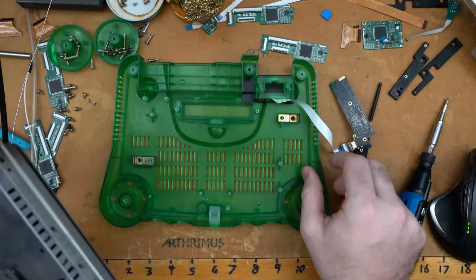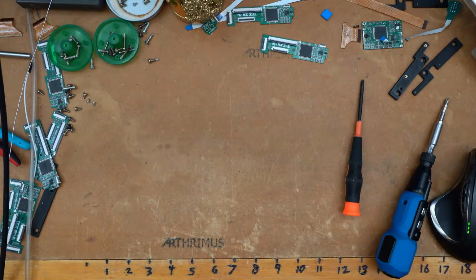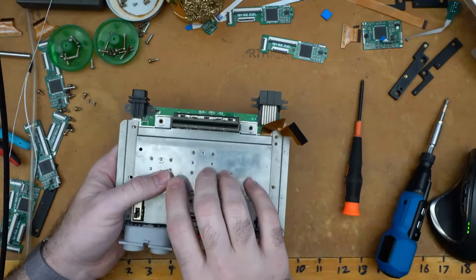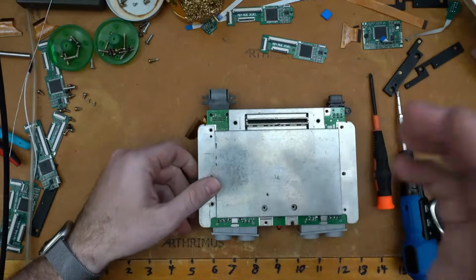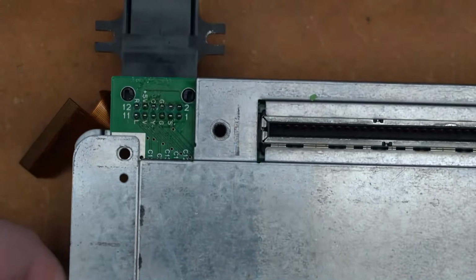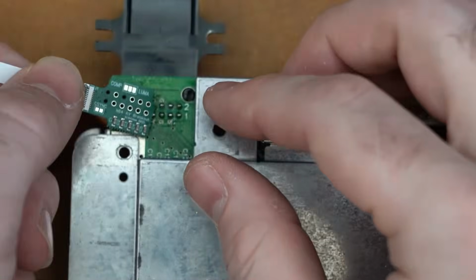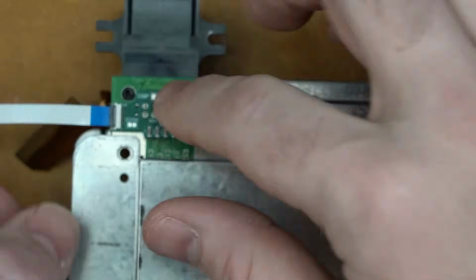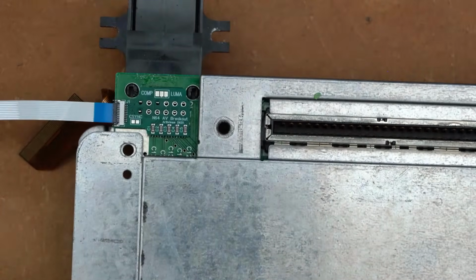All right, so the first thing we're gonna do, now that we've got this all opened up, is we're going to flip over. Now this is a CPU O2 board. That's important when we configure the jumpers for this AV out. So we've got our AV multi-out. We're just going to take one of these multi-out quick solder boards, and you just install it in place like so. And then we're just going to solder all of the points that need to be soldered.